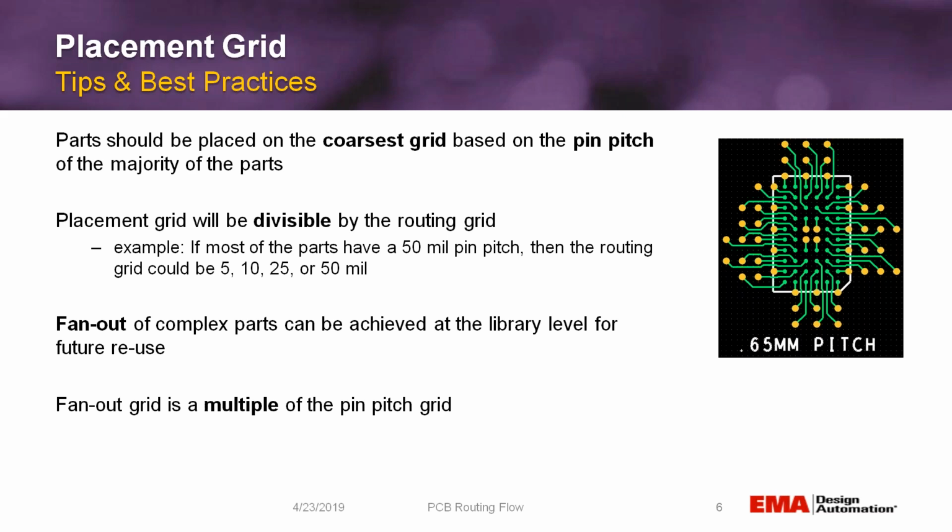Complex parts can also be achieved at the library level. Here I have an example of a 0.65 millimeter pitch part. This is a BGA, a typical, what we would call a dog bone pattern, where it fans out in diagonal mode, does not work in a situation like this. So this is where you can come up with your own pin escape scheme to figure out how to get these signals out to a routing point.